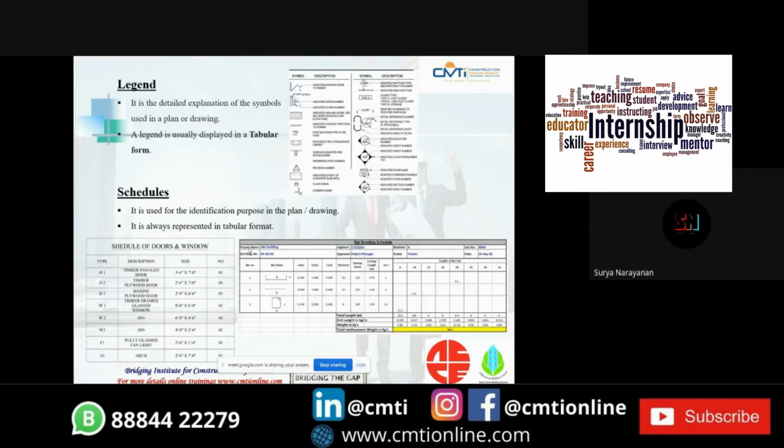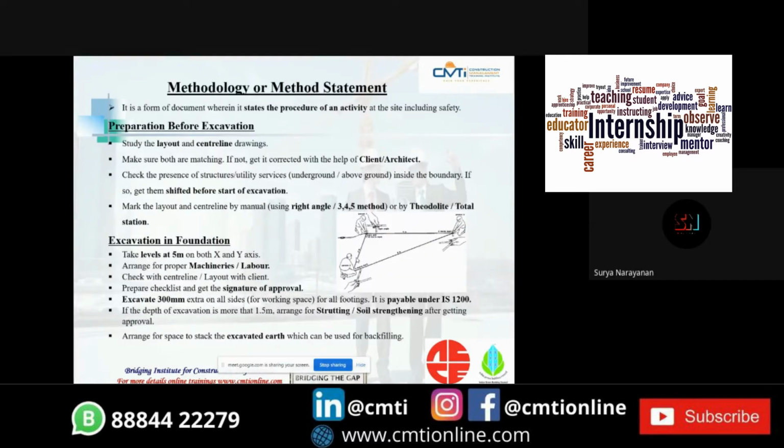So next is schedules. Schedules are also given for identification purposes in a plan because a plan might consist of various different sizes of doors, windows, and ventilators, which also gives information at what sill levels they should be provided and the number of doors to be used, etc. As you can see in this tabular column. And next, bar bending schedules will also be provided in a plan, where we get information like the dia of the bar being used, the spacing to be provided, and cutting lengths and unit lengths to be used.